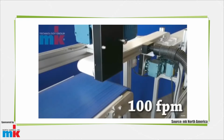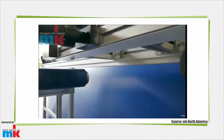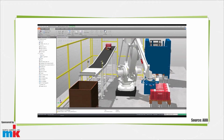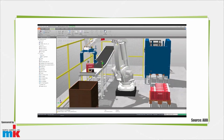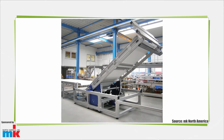Vacuum conveyors work with a perforated belt that draws air through grooves in the conveyor bed plate to hold light or flimsy parts on inclines or during especially fast transport. Some metal-free conveyors have polymer bed plates instead of steel bed plates where metal scanning equipment checks product, usually food, for contaminants. Last but not least, pivot conveyors mount to a base to swing away when workers need to walk through a line. Some controls can automatically resume product flow after the conveyor returns to the inline position.